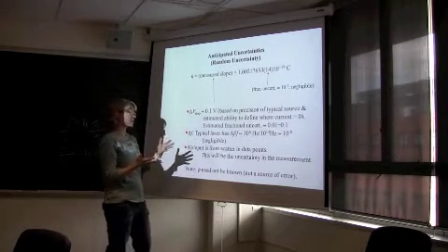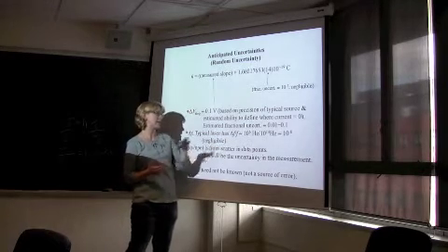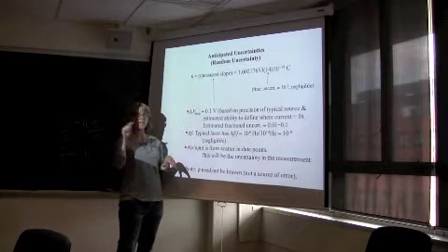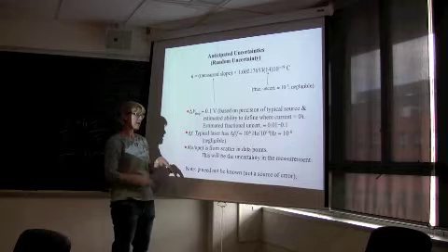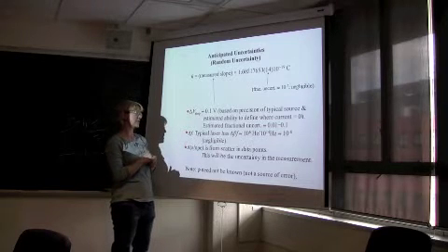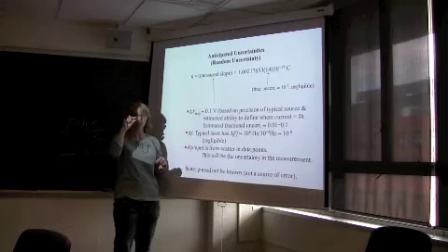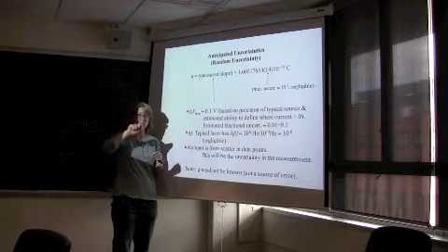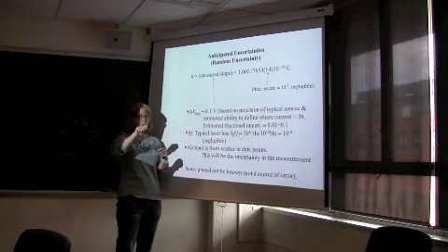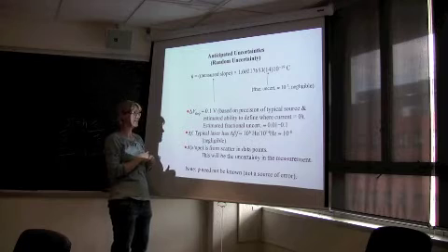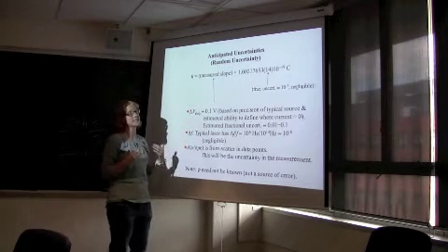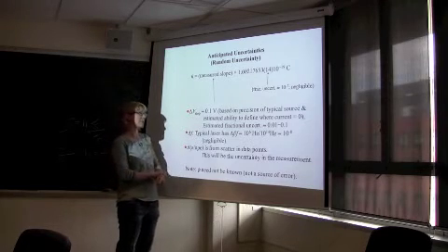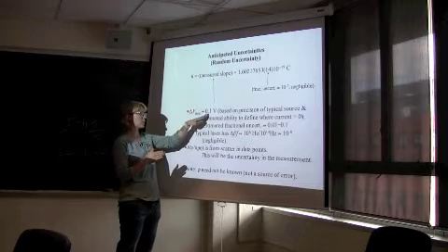And so from those widths, we actually know that it's 10 to the minus 8, but that's also really small, so it's also negligible. There's some error from our fitting in our plot, and this is where most of the uncertainty comes from. And there's also some uncertainty in our ability to actually find V-stop. That has to do with how well you can set the voltage across and where zero is. We did some preliminary experiments on it, and we found that we could estimate getting the voltage to within 0.1 volts.